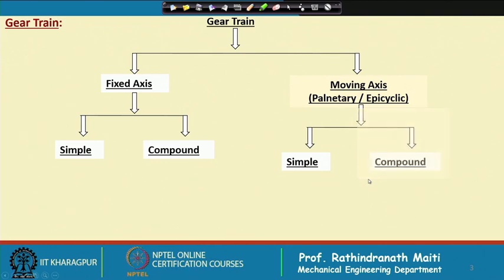And in case of compound gears, in the planet stage there will be one gear meshing with the sun and another gear on the same axis, or integral on the shaft or fixed on the planet carrier shaft. It is driving the ring gear or maybe it is the external gear.